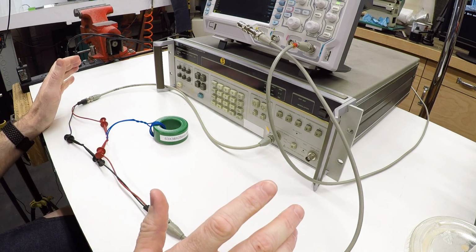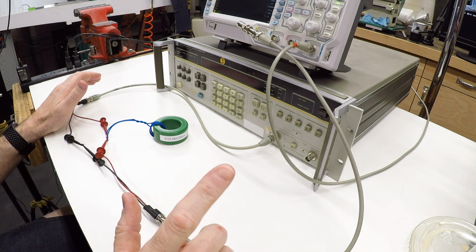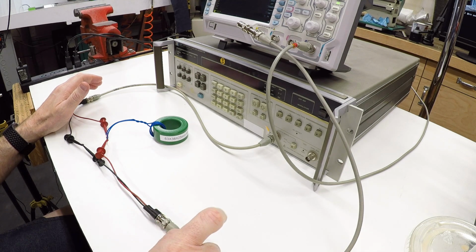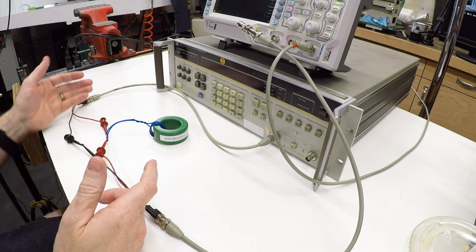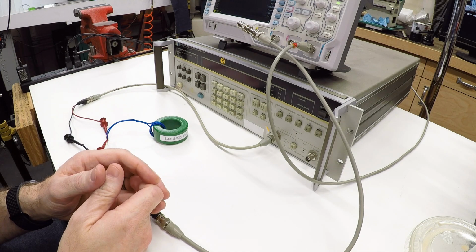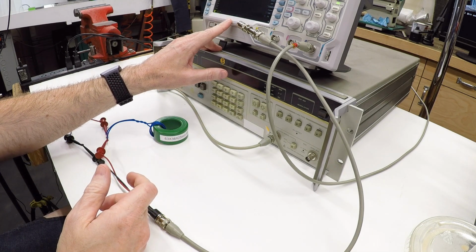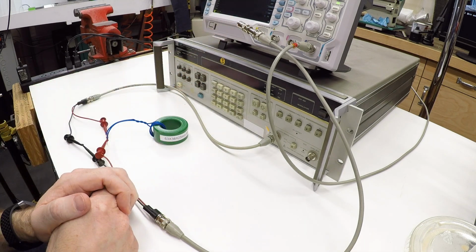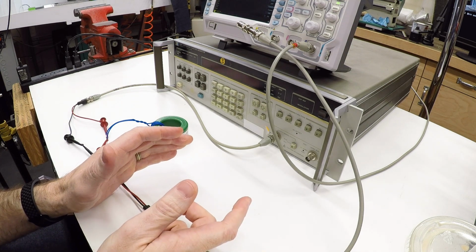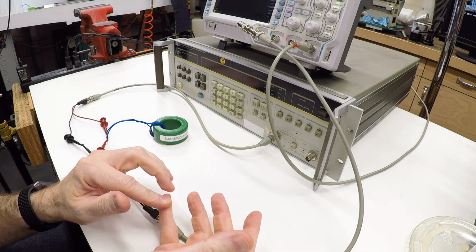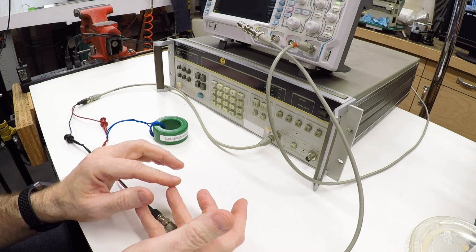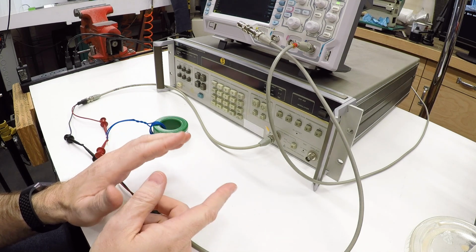We're not going to cover all of that ground today, but in one of the comments, somebody suggested using a white noise frequency source to get a broadband noise signal, run that through, and then plot it with a fast Fourier transform on the oscilloscope. I've played around with the tools that I have. I don't really have a white noise source. I tried to generate some broadband noise with a square wave, didn't really have a lot of luck.